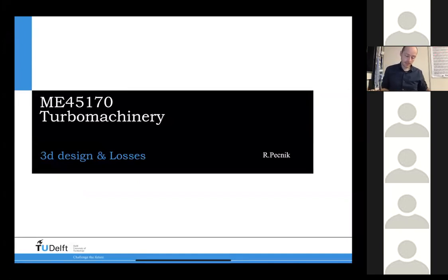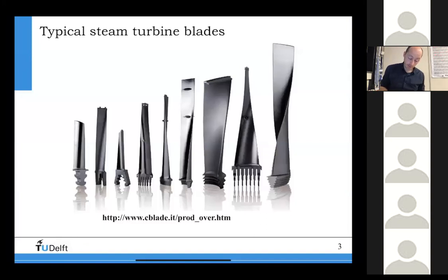But now we can discuss the 3D design. So we have talked about the mean and the middle of the blade. We have been able to define the velocity triangles, the design parameters, and then we are able to discuss also how the performance changes with respect to rotational speed and mass flow. And now we can see how it actually changes across the whole blade length, right?